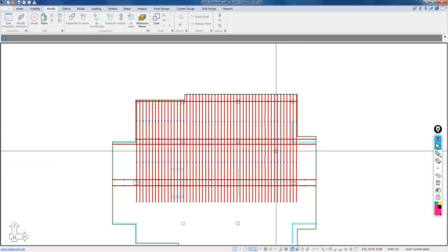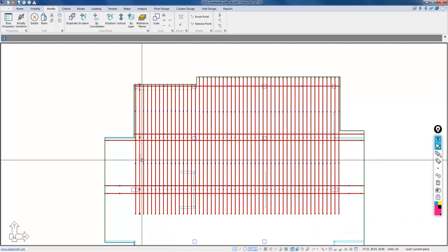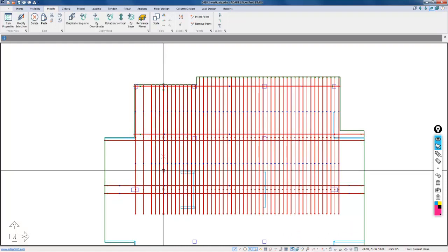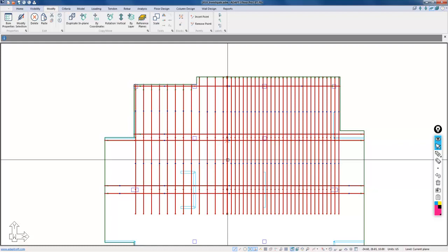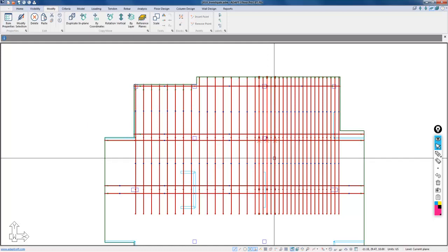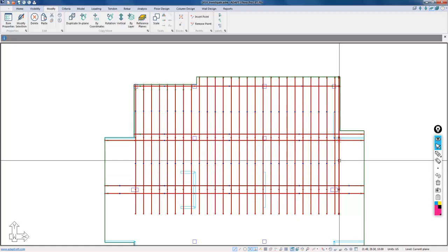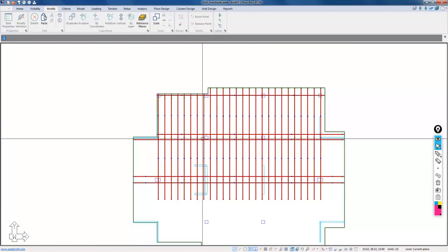Okay, so I think again, I think we have too much PT here, so I'm actually going to delete out. We're going to say we have 2 tendons every 4 feet, and I'm actually going to delete some of these tendons. So we'll delete every other cable, and I'm just selecting and deleting those out. I could also just control. That might be a bit faster. Okay, I'll leave those 2 on the end there. We'll get rid of it. Okay, so we have our distributed now.